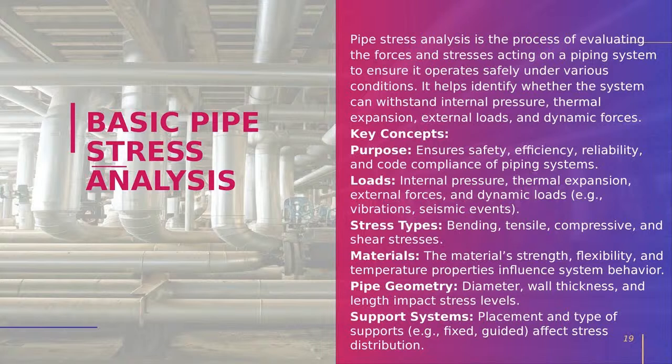We will be using some codes and standards for this, like ASME B31.3, and allowable nozzle loads obtained from the manufacturer. We will consider everything while doing this stress analysis. And then the material, what is the material made up of, and what is the standard of the pipe flanges? Everything we will see in the pipe stress analysis. Pipe stress analysis is very, very important in piping engineering, again and again.